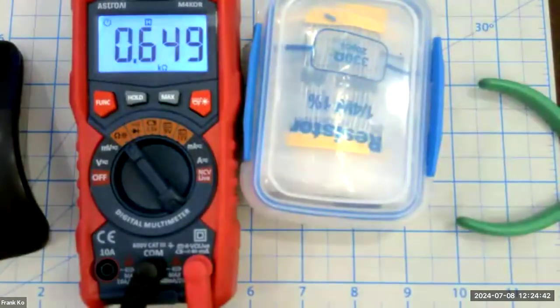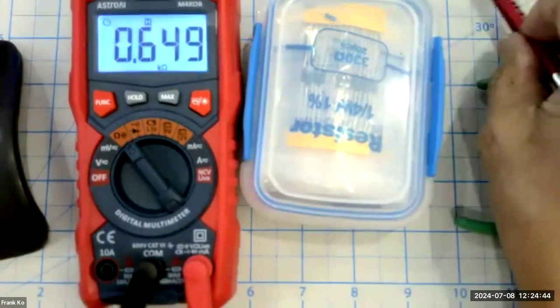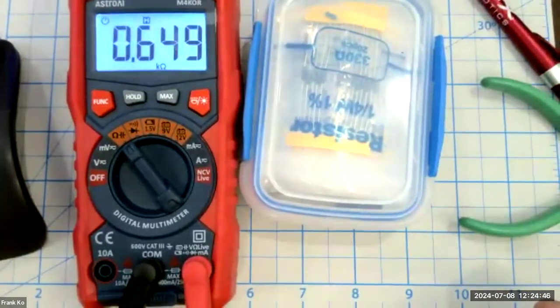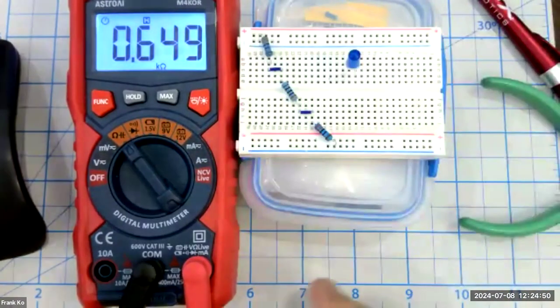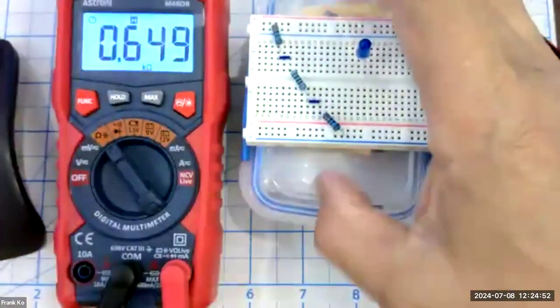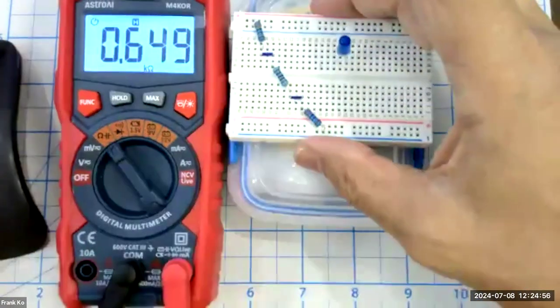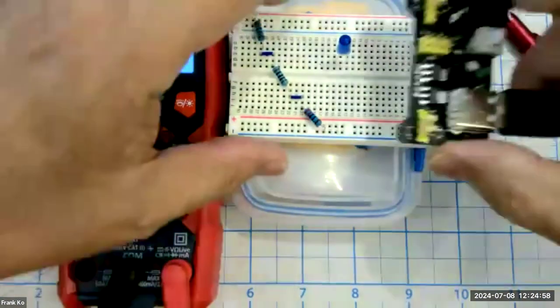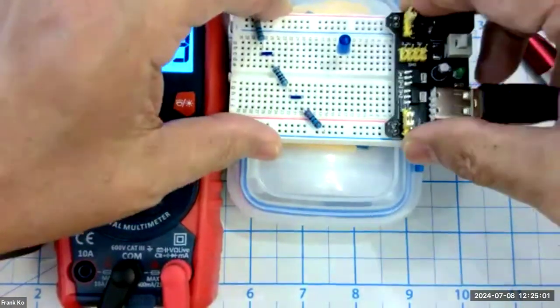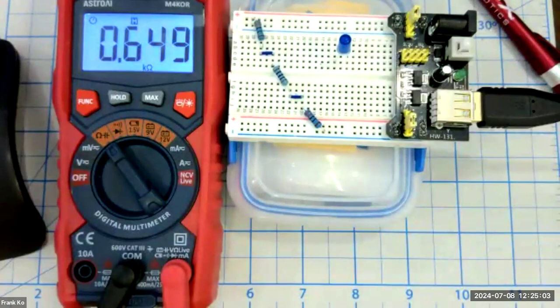All right, now once we verified the ohms, the next thing you want to do is verify the voltage. So we calculated the voltages. So let me bring the puppy back in here. And hopefully you've taken the time to double check your calculations. And let's go ahead, hook the power supply back on. And we were supposed to have something close to 2.54 volts.